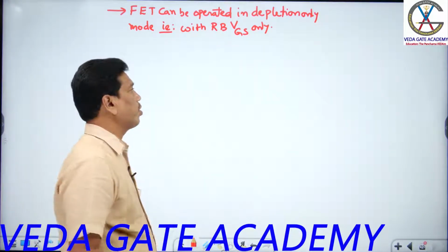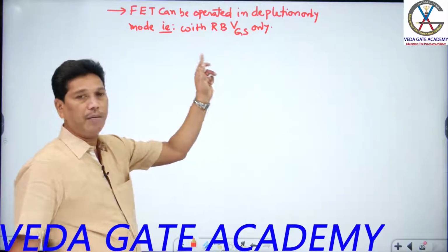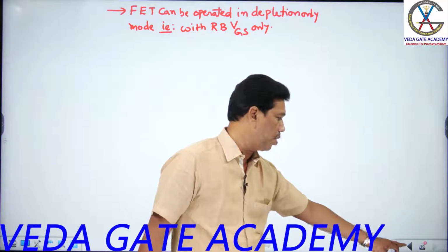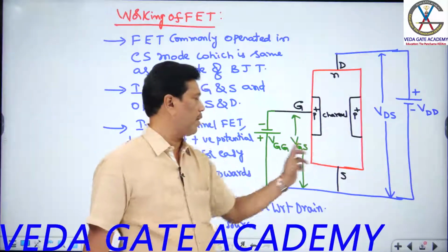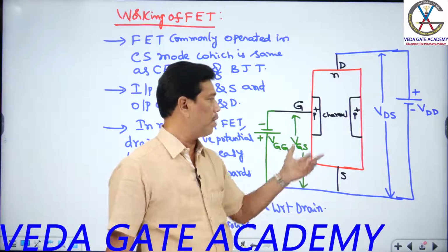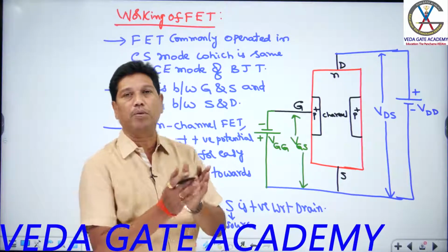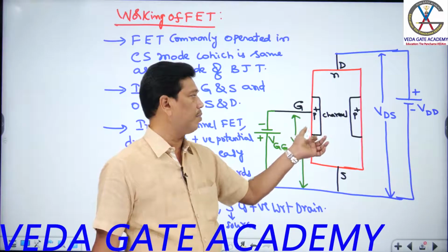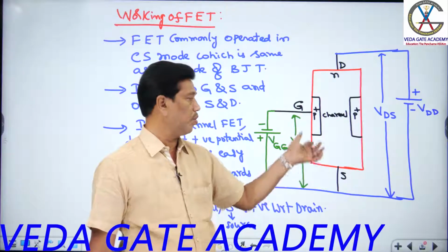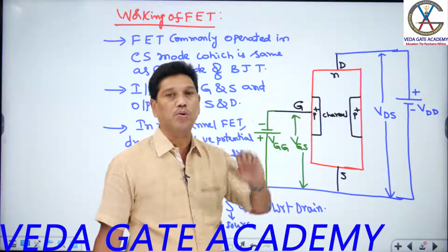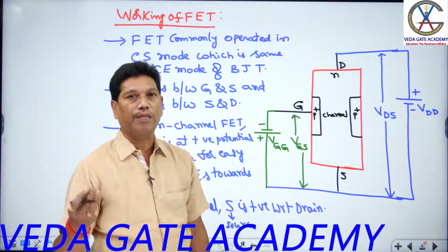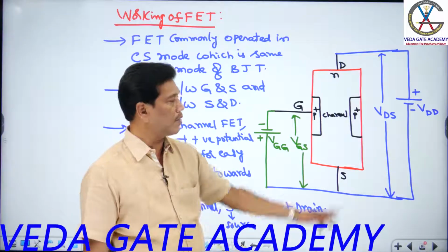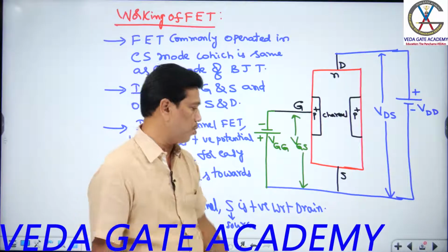Okay. Now I can confirm. First, I can examine what is the effect of each supply on the channel width. See this one now. So two supplies are present, right? One at input, the other at output. Now instead of presenting them both at the same time, both acting simultaneously, I can present them independent of each other. So in one case, one source is present, in the other case, the other source is present. By that, I can discuss the effect of the supply on the channel. First, I can go with respect to gate voltage. Next, I can go with respect to drain voltage, students.